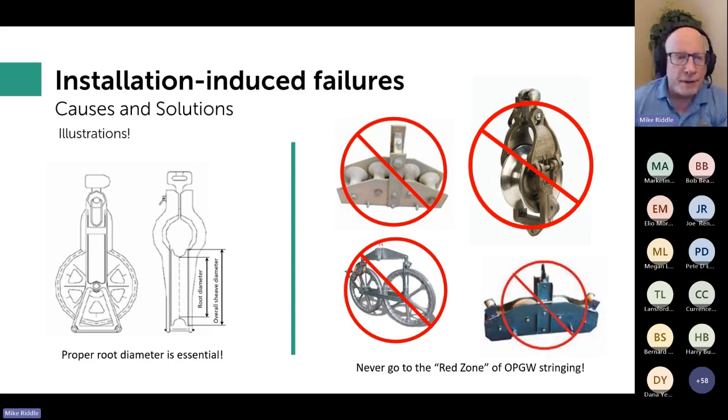It's not in the scope of today's presentation. I do discuss it in the installation presentation, why that isn't true. You basically have a circle here, and if there's not enough bearing surface over that circle, then it doesn't matter how many blocks you use. If you don't have enough bearing surface on one circle, you don't have it no matter if you use 10, because the bearing surface just gets divided by the number of blocks that you have of a given size.